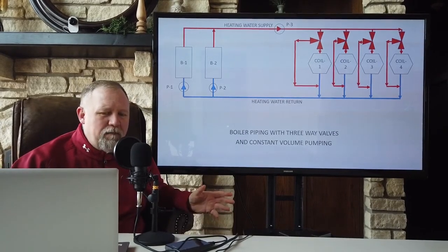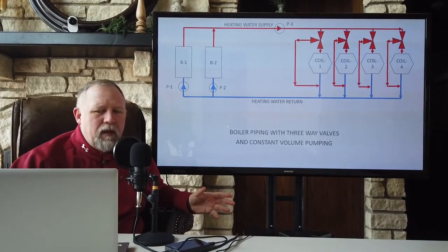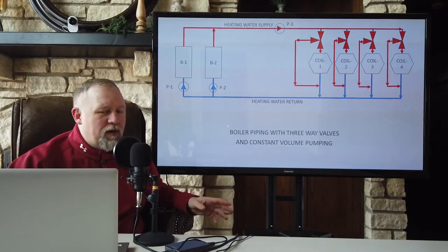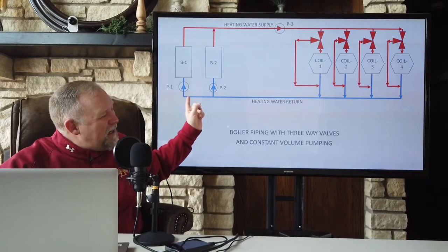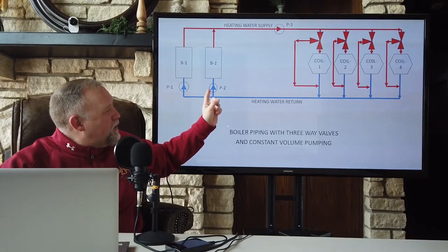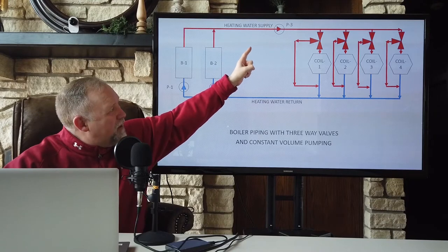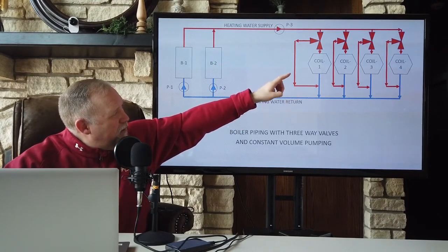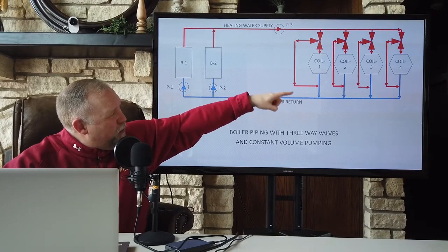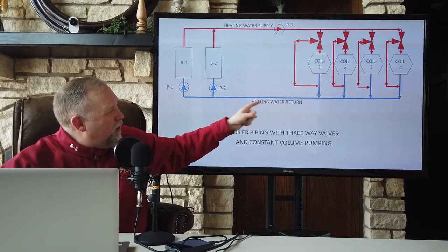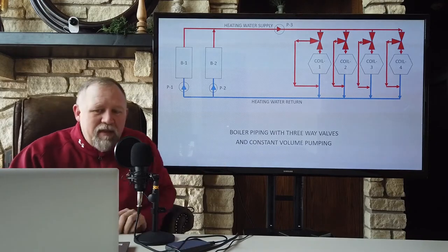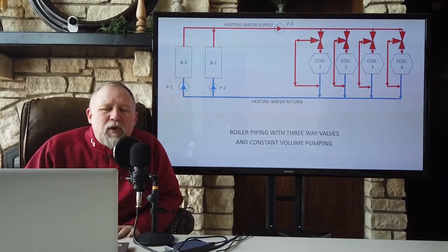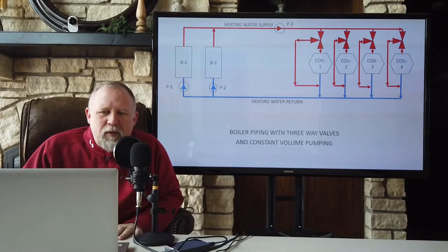So let's use our million BTU per hour input with a 90% efficient boiler. That means pump 1 is pumping 90 gallons per minute. Pump 2 is pumping 90 gallons a minute. And then pump 3 is pumping 180 gallons a minute all the way out to the coils. The 3-way valves can either send water through the coil or around it and then all the way back. Like I said, the distance that pump 3 might have to pump could be miles. Who knows, in a large building.